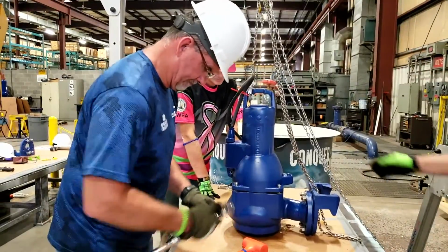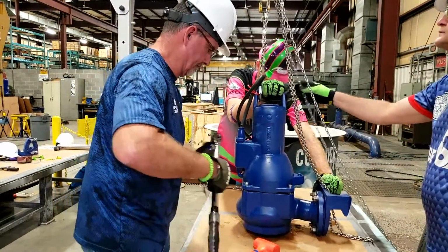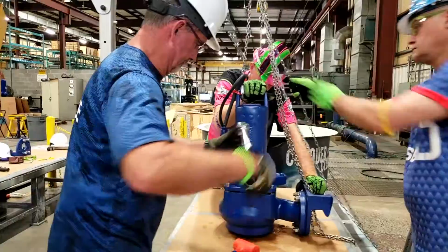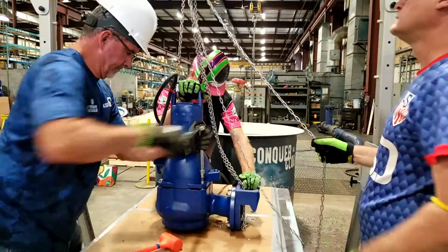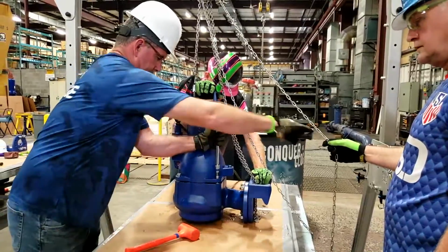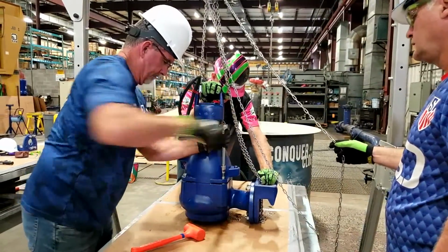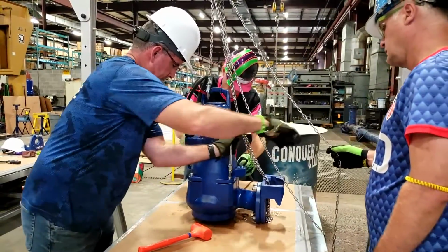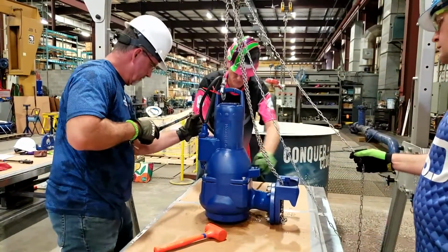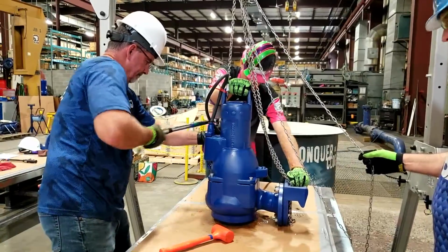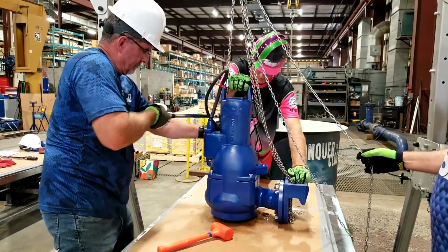Once the volute bolts are hand tight, using only the torque wrench, torque them to 25 foot-pounds in a crisscross pattern. Be sure to use the correct torque wrench. You may not use the ratchet at any point to reinstall the volute bolts. You will not be penalized for using the torque wrench as a ratchet while reinstalling the volute bolts, provided you got them hand tight first.